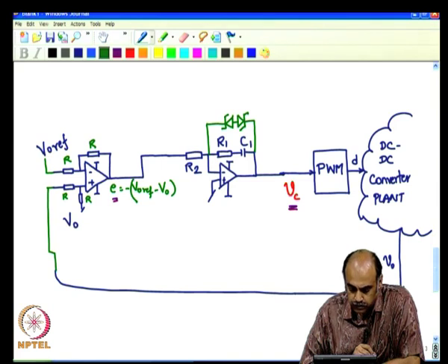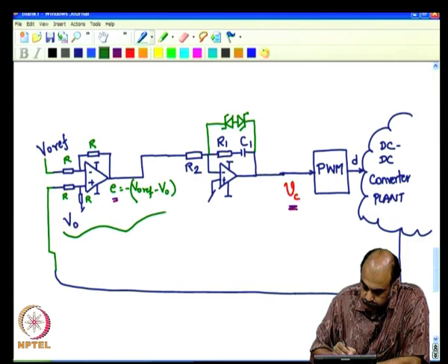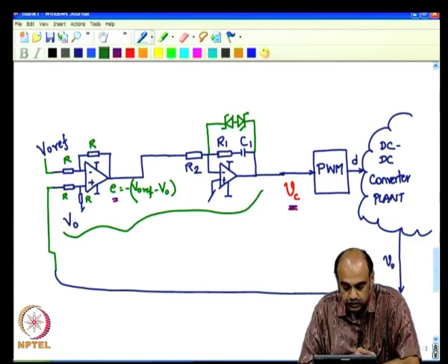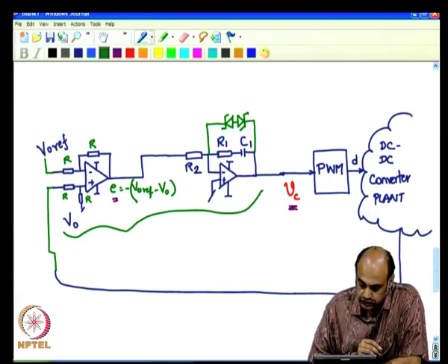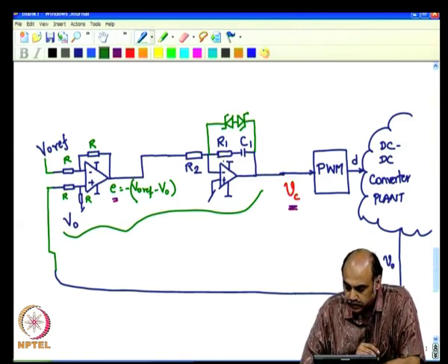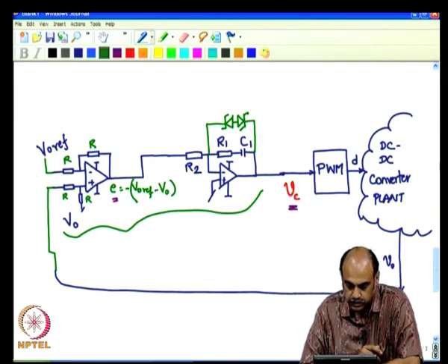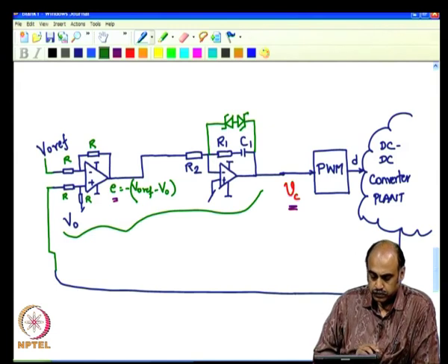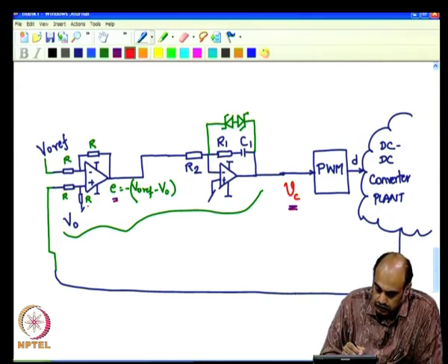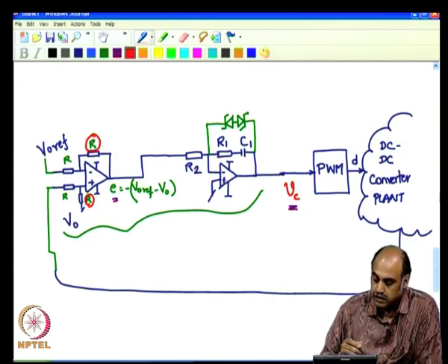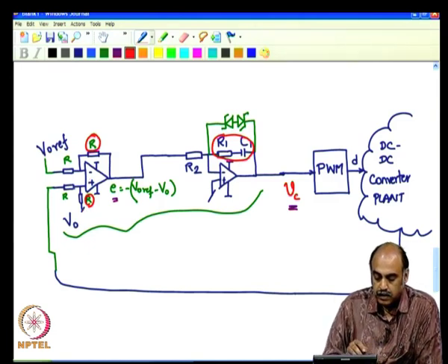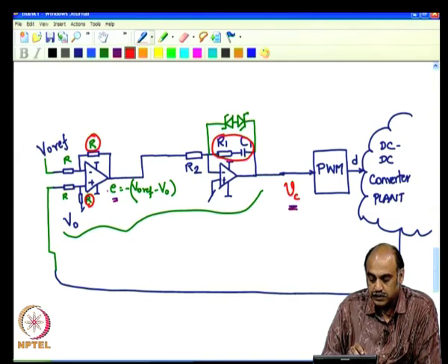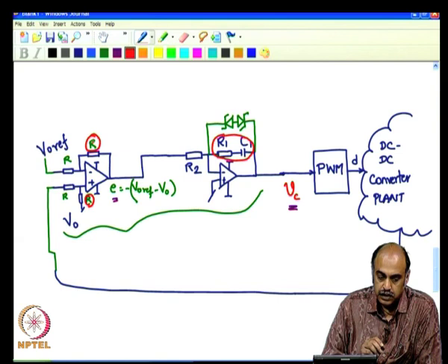Now, if you observe, can we do something such that these two op amps can be combined together and made into one single op amp? This is nothing but a difference amplifier, and this is nothing but an inverting amplifier with impedance gain, a gain which varies with frequency, not a resistive gain. So, if we look at these two resistances, convert them to impedances of this type both here, then they become a difference amplifier, and additionally they can also do the integration.